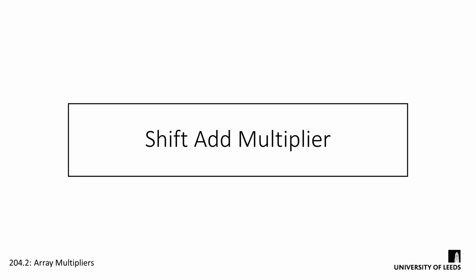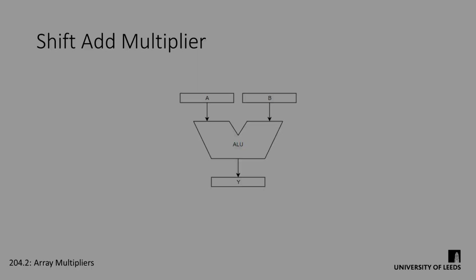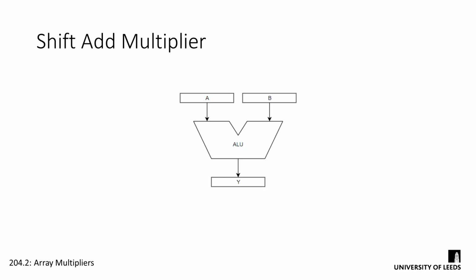The fastest way to add multiplication functionality into a system that we already know would be to develop a shift-add multiplier. A shift-add algorithm generates one partial product per cycle and adds it to a cumulative total of the previous partial products. As we only need to perform addition, we could take our trusty ALU from last year and rewire it to allow this algorithm to be performed.